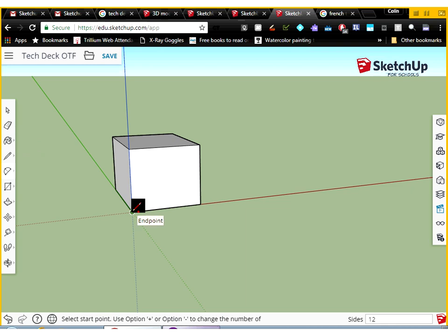and I'm going to start at the bottom here because I want the ramp to not have a gap to it. And I'm going to click a spot on this top line. So I don't want to go all the way to the edge because on a real ramp you'd have a bit of a platform on the top. Click there, and then you can see I can bend this line.